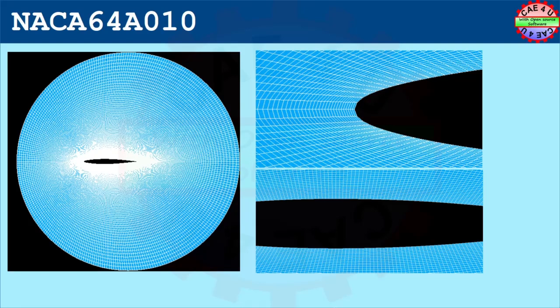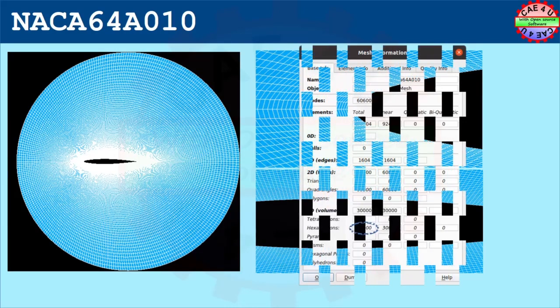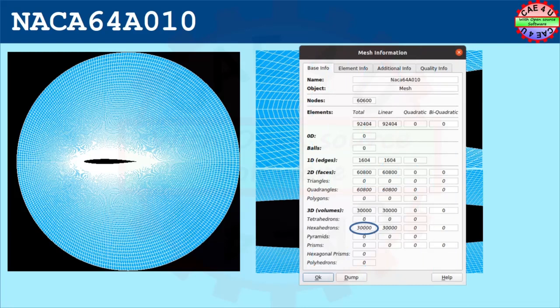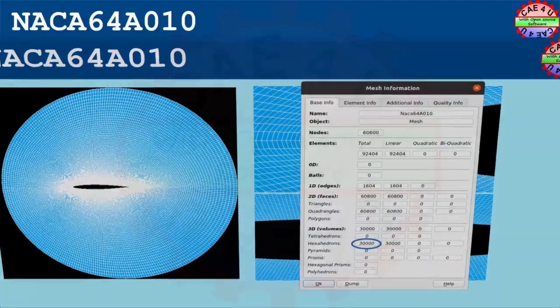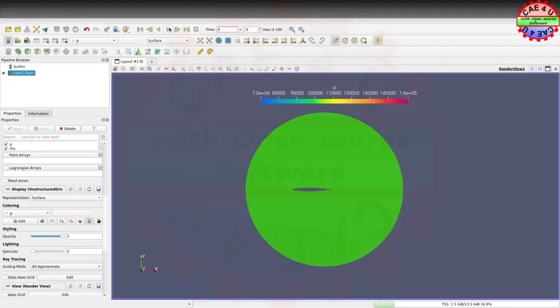Interestingly, the simulation indicated the refinement would be more advantageous at the body region than at the trailing and leading edge, and a coarse mesh can also help in smearing the shock waves which is observed in the test data. So we are going to use a modest 30,000 cells for this simulation. Before we go further, let us look into the flow field for both cases quickly.